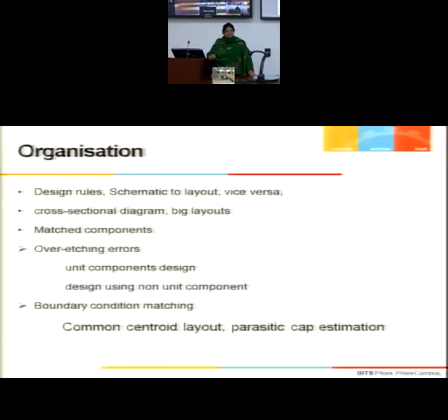So how to control dimensions? Certainly absolute dimensions you cannot change, but it is a ratio that we control. So let us understand the two conditions because of process variations as listed. You mainly have overetching errors, overetching, undercutting, or if I look at the diffusion process, then the diffusion moving in an isotropic way in all four directions, thereby increasing the length and width of your drain and source junctions.